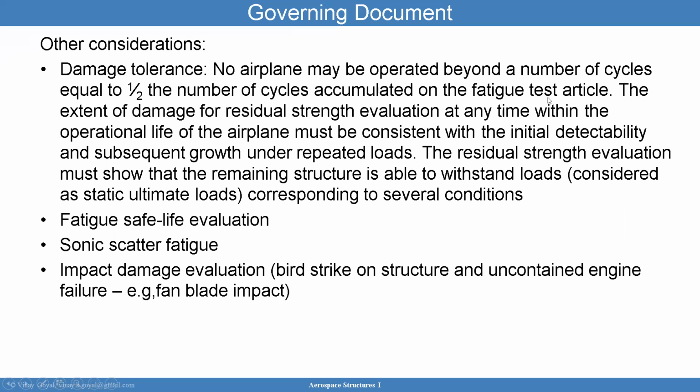Other consideration: no airplane may be operated beyond a number of cycles equal to half the number of cycles accumulated in the fatigue test article. Now, this looks different from the launch vehicle philosophy, which is 4x, but here you're also doing inspections quite a bit and your analysis is a little more conservative. The residual strength evaluation must also show that the remaining structure is able to withstand loads corresponding to several conditions: fatigue safe life evaluation, sonic scatter fatigue, and impact damage evaluation, like bird strike.